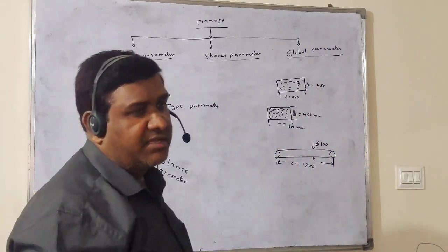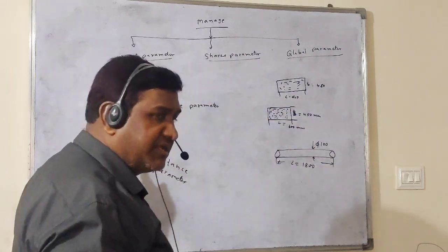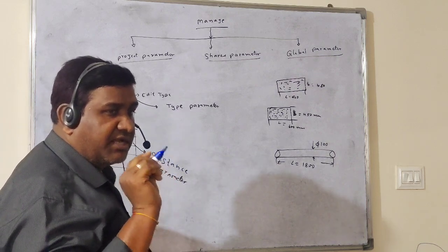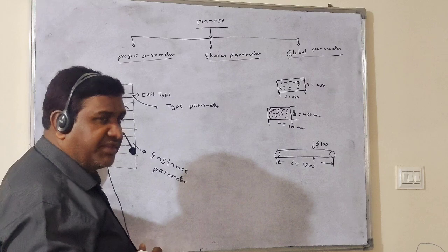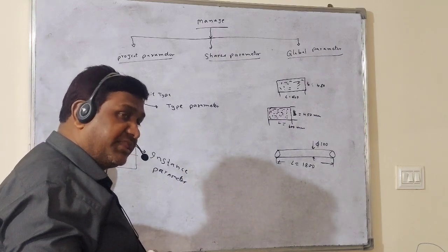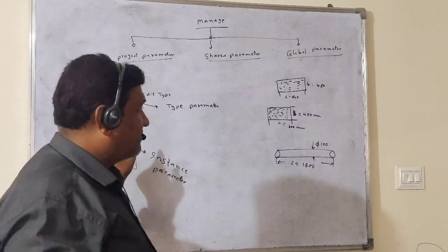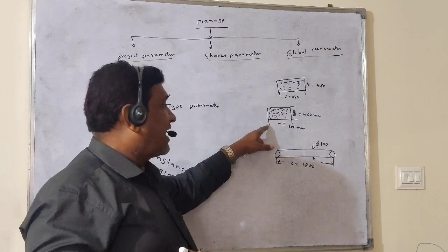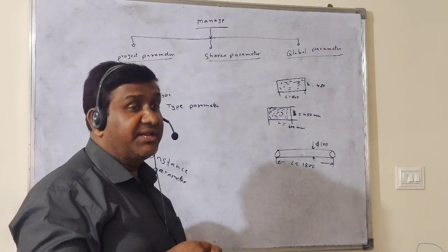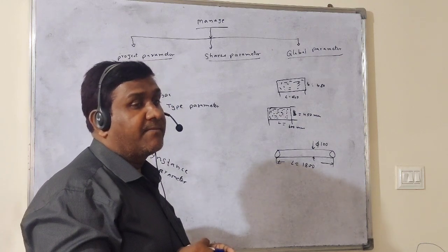Now, these parameters, the length and width, are directly visible in the properties toolbar, because if you click the column, the length, width, everything will be visible there. Then whatever values you change directly in the properties toolbar, the size of the column is automatically changed, and that change will be reflected only in the selected component.